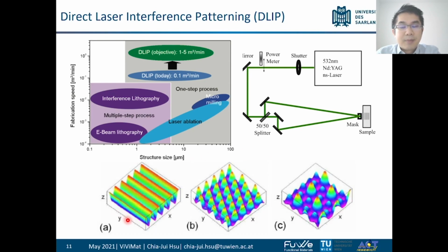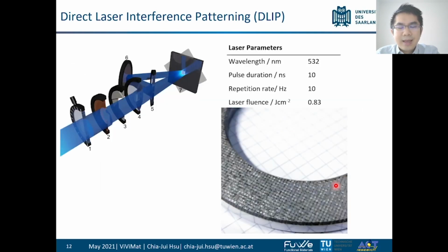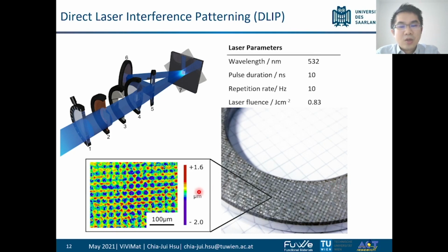By modifying and adjusting the angle and the distance, we can have, for example, line-like structures, dot-like structures, and more complex ones. The idea of having these patterns on the surface is, of course, not to damage it. Actually, we try to create pockets on the surface, and when the contact has insufficient lubrication, the oil and lubricant in the pockets can go out and play the role. This is what we are going to do, and we'll find out in the results part.